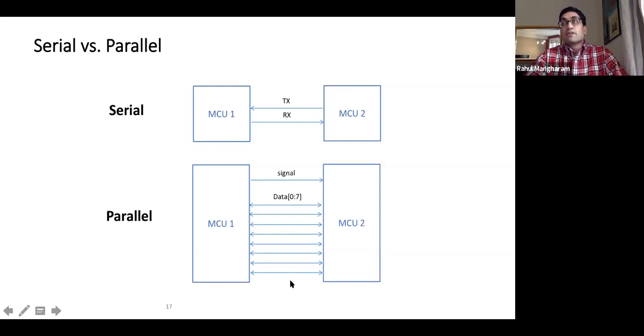And that's why we switched from 8-bit microcontrollers to 64-bit processors, because 64-bit processors can get data across from memory to the CPU much faster. But what is the cost for that? The cost is that you have to have more pins. That means you have to have more physical space allocated to that, and space is always at a premium, because we are trying to make these chips as small as possible with as few pins as possible.